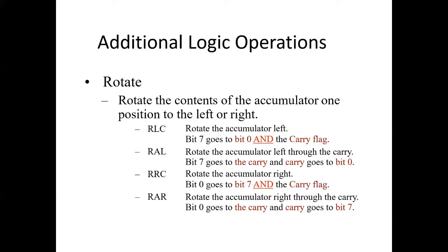We have to notice that carry flag is not involved in the rotation and it is only 8-bit rotation of accumulator contents. Only carry flag is affected by this instruction execution. This instruction is useful to check the value of the MS bit of accumulator: perform rotate left, and the carry flag will be affected. It is also useful to perform multiplication by 2, rotate the accumulator to the left. It works correctly for unsigned numbers as long as the MS bit of accumulator is a 0 before a rotation.